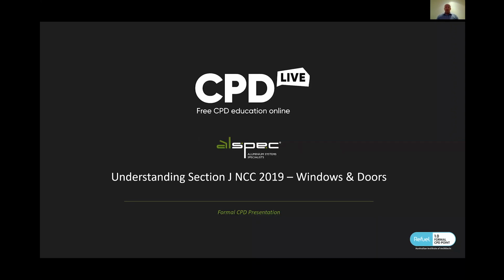So the presentation itself is about the performance requirements of Section J, and it's about understanding where it applies. We're going to look specifically at the U values and solar heat gain coefficient, and we'll be looking a lot at the window to wall ratios, which becomes an important factor in Section J NCC 2019. We'll be looking at some component performance, be that windows, walls, spandrels. We'll also take a look at shading and how that impacts overall performance. We will spend a bit of time looking at some models and how facade performance, be that windows, walls, doors, affect your overall performance and how that might impact your window to wall ratio and designs moving forward. We'll look at some examples of some buildings that have currently already been built, and finally we'll look at some solutions. Okay, so I will make a start.